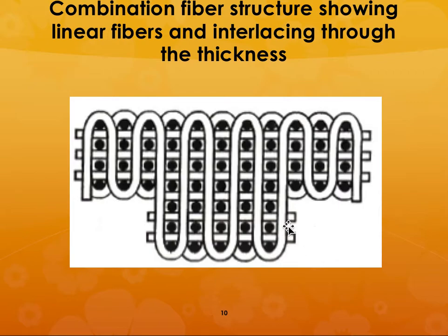You can also have a three-dimensional weave. So you have fibers in the 0 direction and in the 90-degree direction, and then you have fibers that are interwoven like this in order to get better three-dimensional properties. But what would be the difficulty in this kind of layer structure? The porosity of this kind of preform would be very directional, which means it will be difficult to infiltrate with a matrix resin. So even though the three-dimensional fibers are going to give you good properties that are almost isotropic in nature, you probably do not find this very commonly.